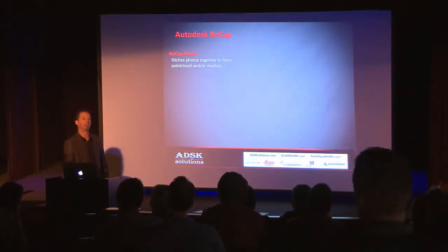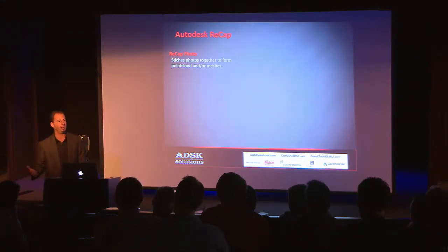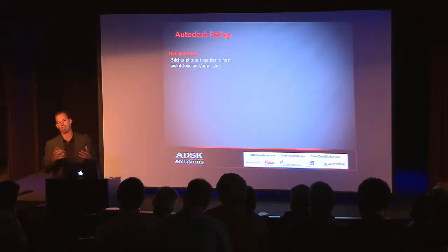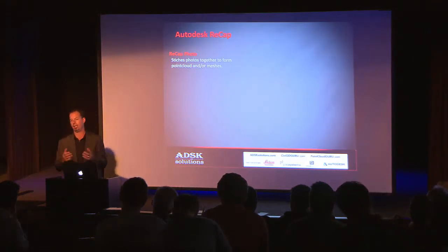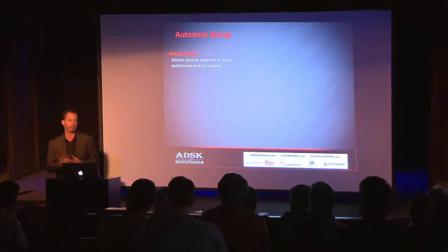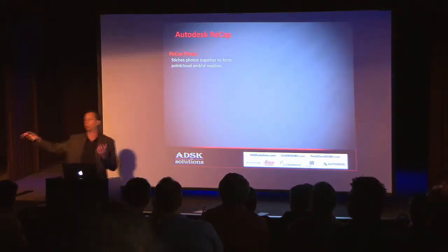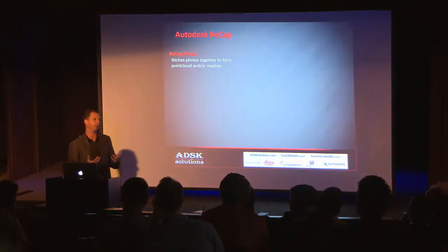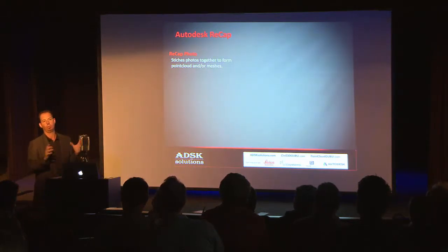No, it's been fixed. So what Eric's speaking about, if you went out, special civil engineering and mobile scanning, you collect data on real world coordinates. What would happen is you would bring it into Recap and it would look, I called it like tiger striping or spaghetti, and people would call me, this product's horrible, I'm never going to look at it again. It was because the origin was so far away from zero, right? Wherever that real world coordinate was, it didn't look good. You could reset the coordinates and it would fix it, but a lot of people didn't know that. So it has been fixed. You can download the latest version, 2015, and you won't have any problems.